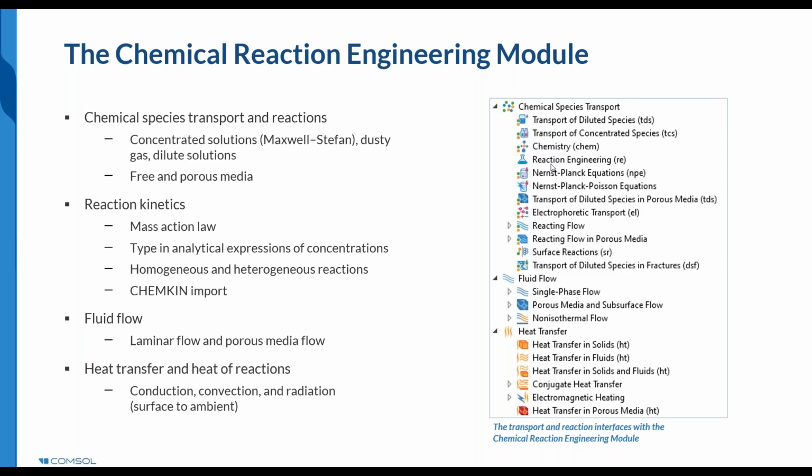reactor system. This assumes a perfect and well-mixed reactor. And while this is not the case for our biosensor, it can be used to quickly generate the required physics interfaces in a space-dependent model. Once we have the reactions defined in the reaction engineering interface, a 1D, 2D, or 3D space-dependent model can be generated from it with the related reactions and transport properties already pre-populated with the necessary reaction data.